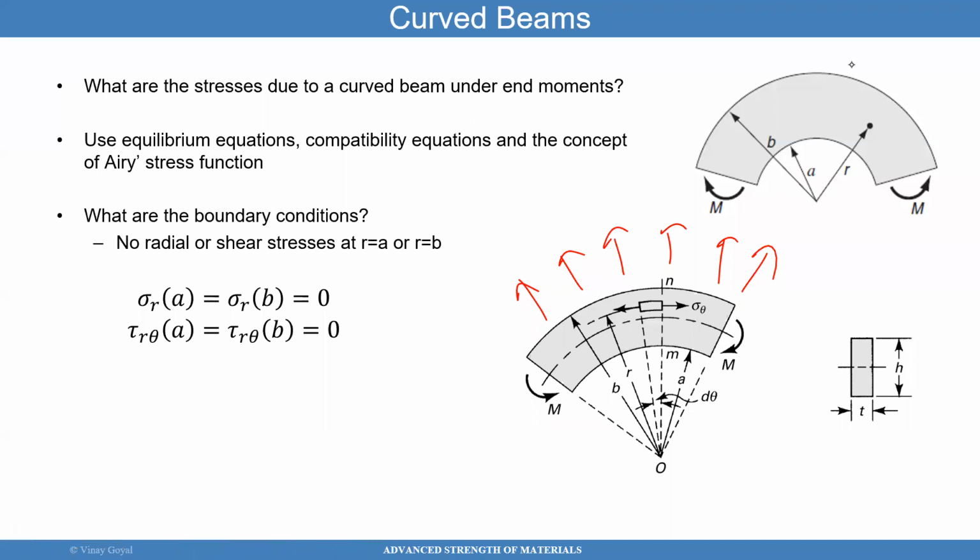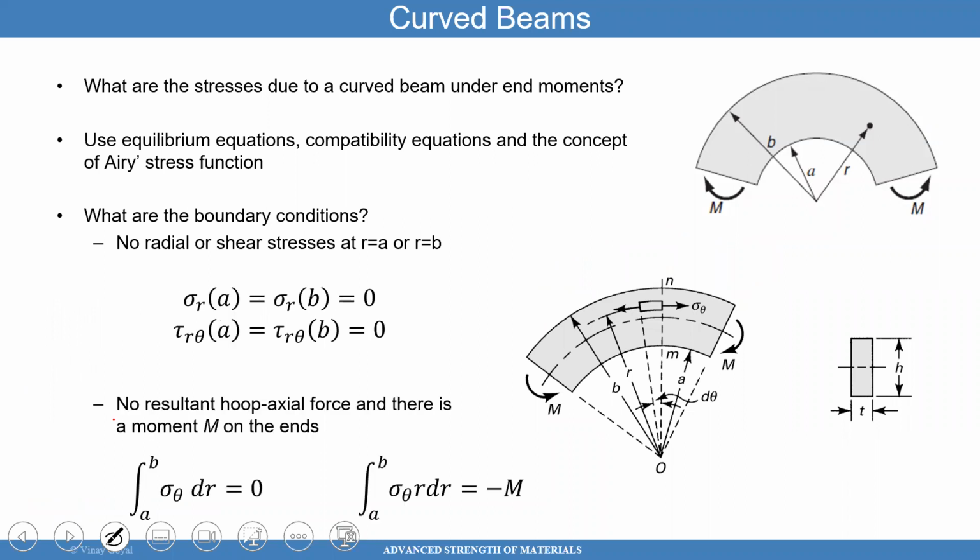Okay, so given that we got the boundary conditions taken care of, if you had a situation where you're looking at the solution for a problem of a curved beam under bending load and pressure loads applied on the top surface, what you will do then is use superposition, because you know the solution for a problem of a ring under pressure. We know the answer to that. So now make sure that's clear to you. And I think we got that right.